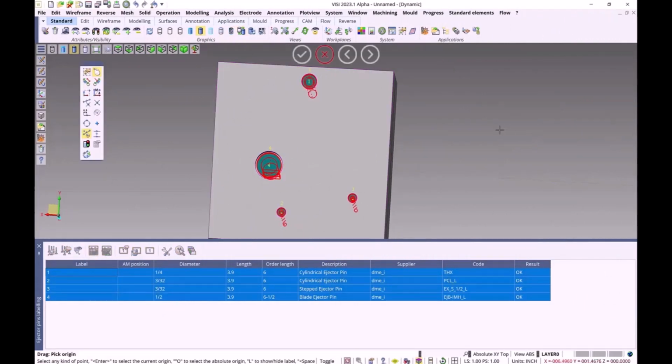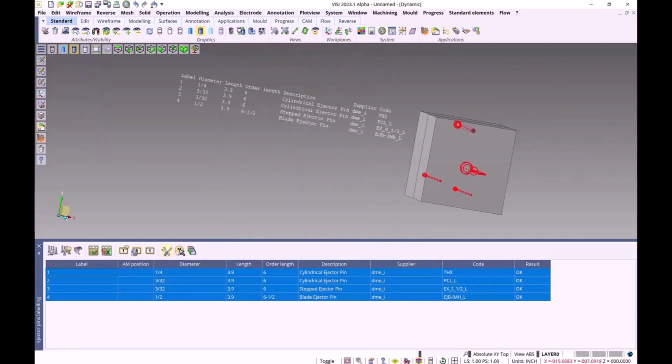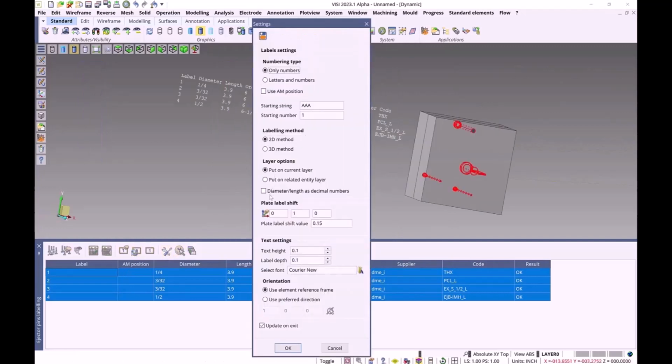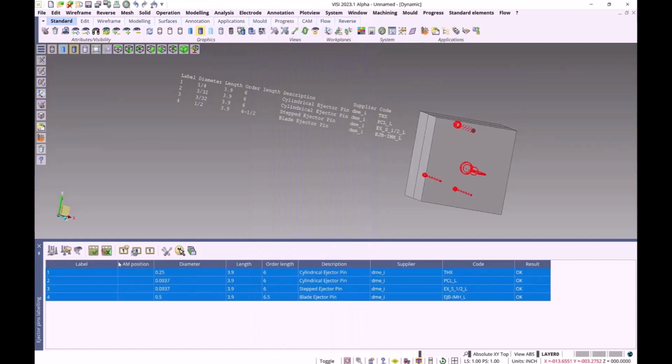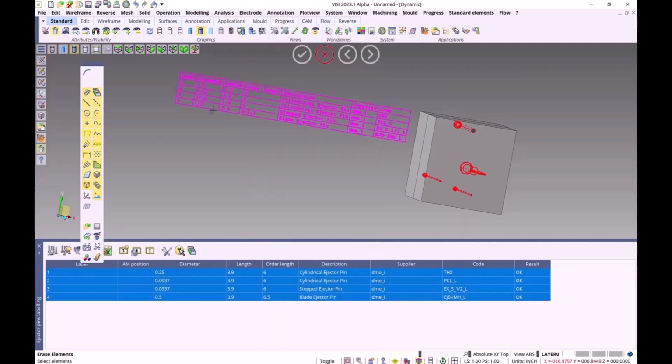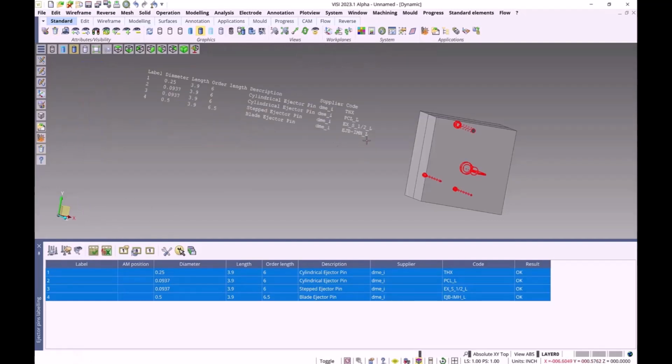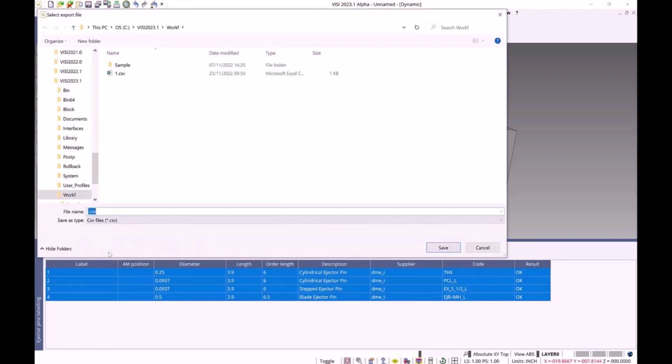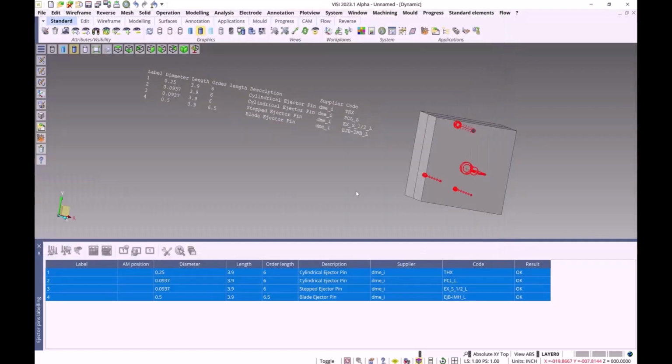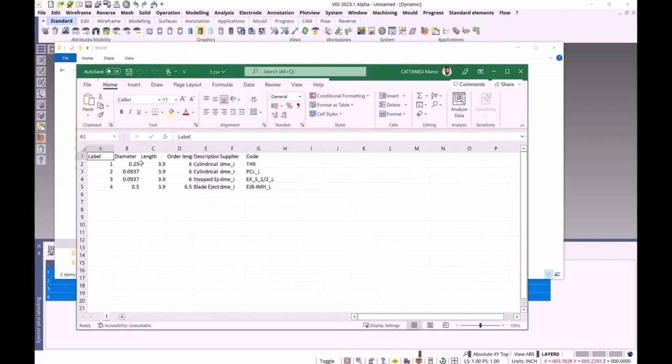So in this example, if I go ahead and, let's say, plot a table out, I can edit the diameter values for that table, and I can edit these lists. You can see how we change it from a fractional value, delete the table, re-add the table, and you can see how that decimal place value is now displayed as a decimal rather than a fraction. So you can edit those at one time. They do update in the CSV file automatically, and it basically edits all of the ejector pin labeling at once.